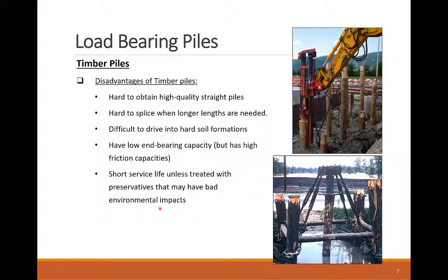However, timber comes with its own problems as an organic natural resource. You cannot obtain low tolerances in timber piles as they are not 100% manufactured with human enforced quality controls. It's not typical to use timber piles in foundations that extend beyond their maximum lengths of around 45 feet.